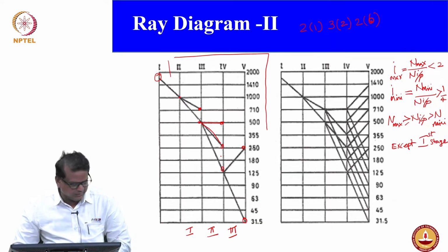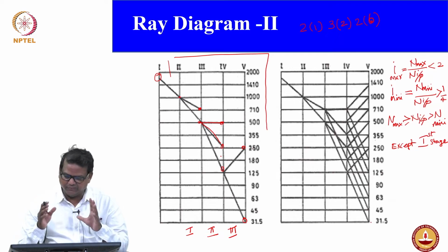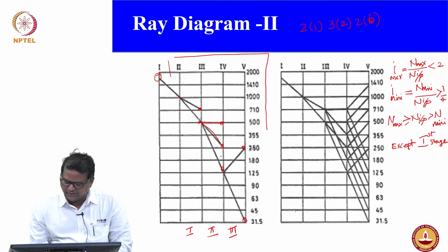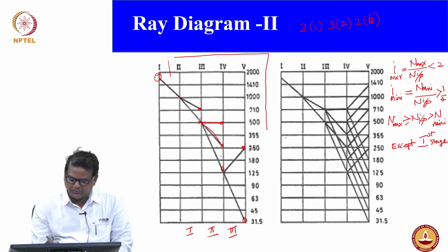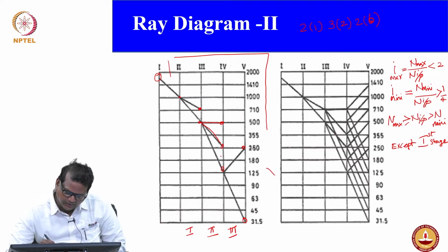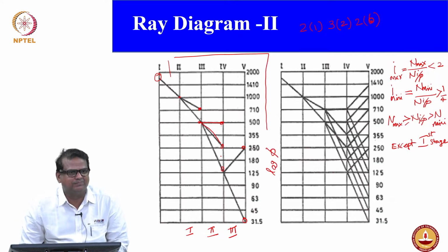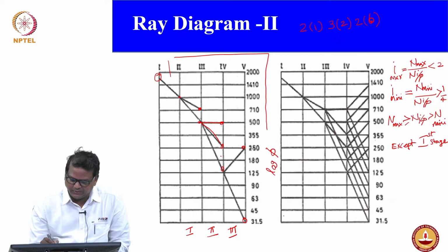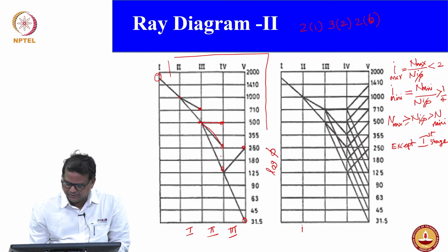I need to give one more piece of information. As you are aware, the vertical position indicates the step ratio in logarithmic format, log phi. In fact, the vertical lines indicate the shafts. So this should be the input shaft and this should be your output shaft.